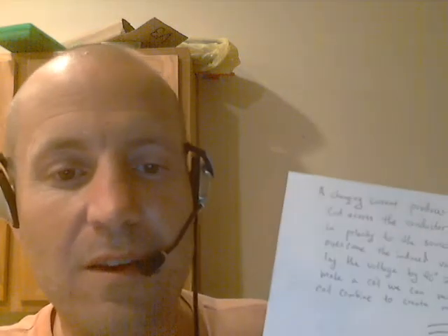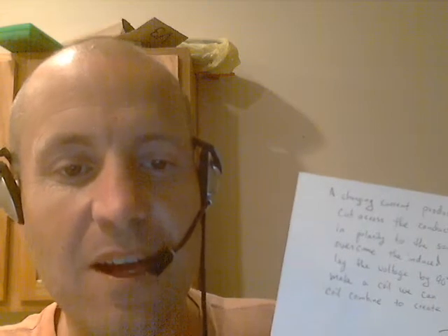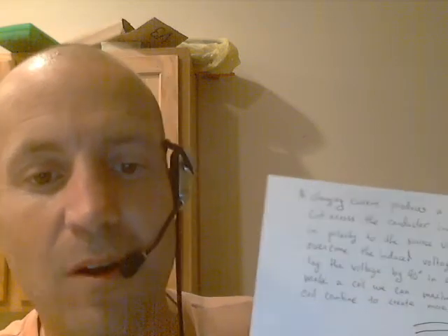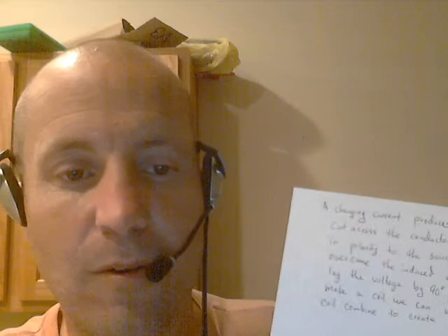Okay. You can also take a magnetic core and put it in the center of the coil, and that will also concentrate the magnetic flux lines, and that will ultimately also increase the inductance of the coil. So there's some things that we can physically do to the coil itself to increase its inductance value. Inductance, by the way, is measured in a quantity referred to as henries. And the larger the inductance, the more opposition to current flow that you can get out of the coil.